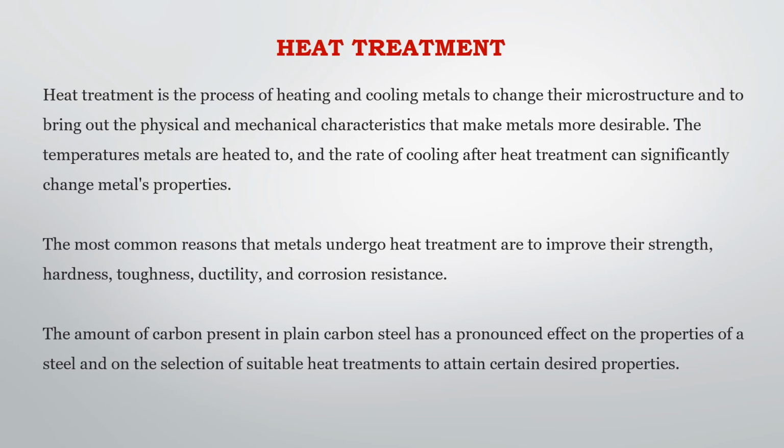Heat treatment is the process of heating and cooling metals to change their microstructure and to bring out the physical and mechanical characteristics that make metals more desirable. The temperatures metals are heated to, and the rate of cooling after heat treatment can significantly change metals' properties. The most common reasons that metals undergo heat treatment are to improve their strength, hardness, toughness, ductility, and corrosion resistance.